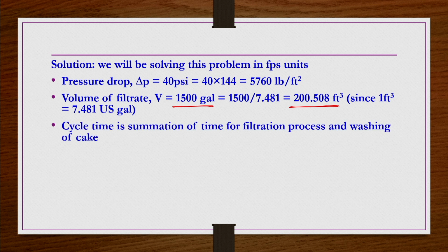Cycle time is the summation of the time for the filtration process and washing of the cake, along with all other times of draining, filling, and then dumping and closing. All those times are added together to get the cycle time.